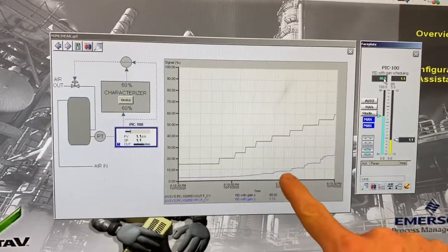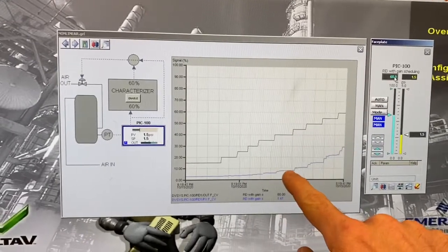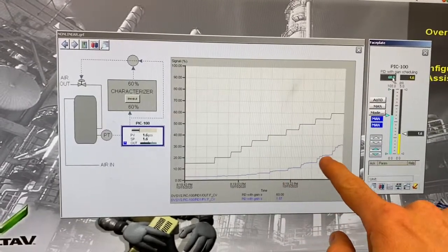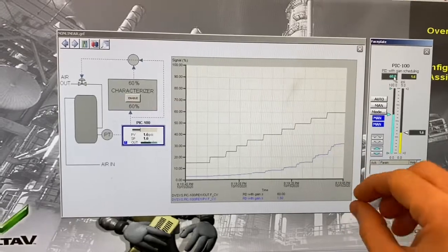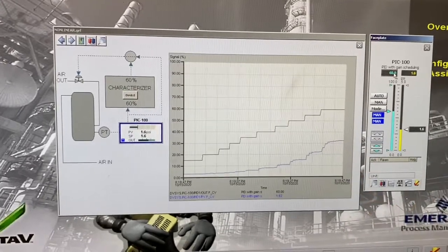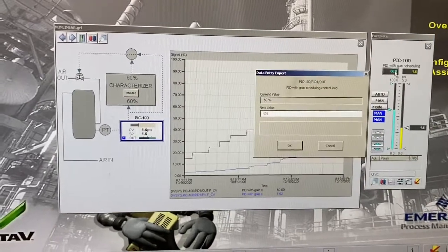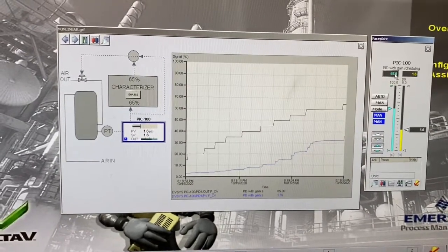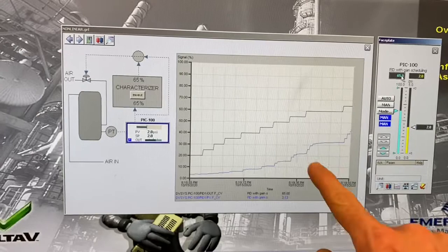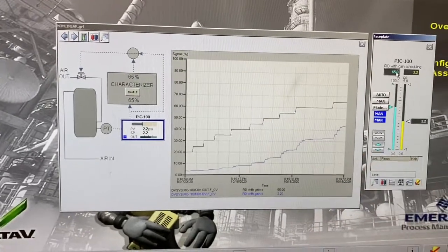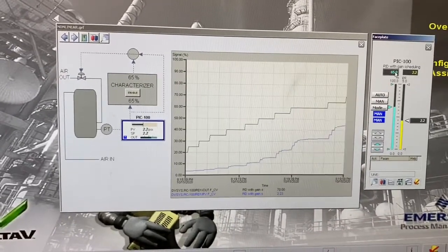But what you can see here is from steady state to steady state, our steady state gain value is increasing. When we increase the input to the process, the output, the PV, is really starting to change. Especially when we get to 60 and 65 here, we've had some pretty big jumps, right? So this confirms that our process is nonlinear.